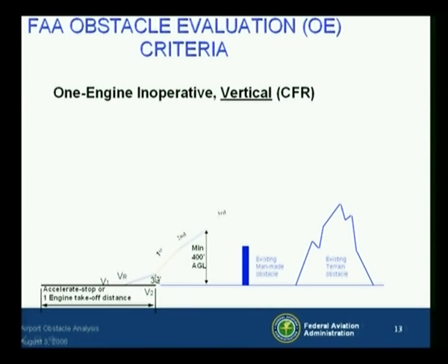The first segment ends when the landing gear is up and locked, and then the second segment begins. And the second segment is the gear is up, V2 speed is constant with this 2.4% minimum climb gradient I mentioned earlier. And then the flight path between these 2 extremes begins to vary quite a bit.